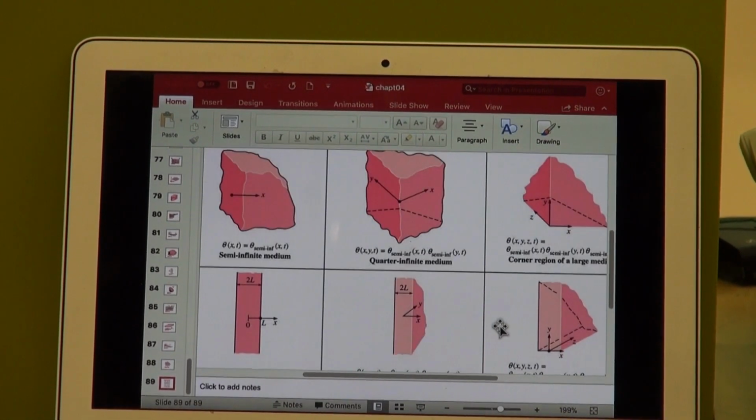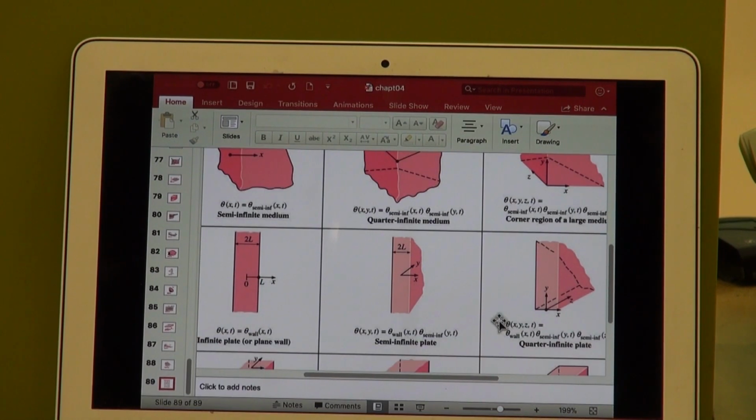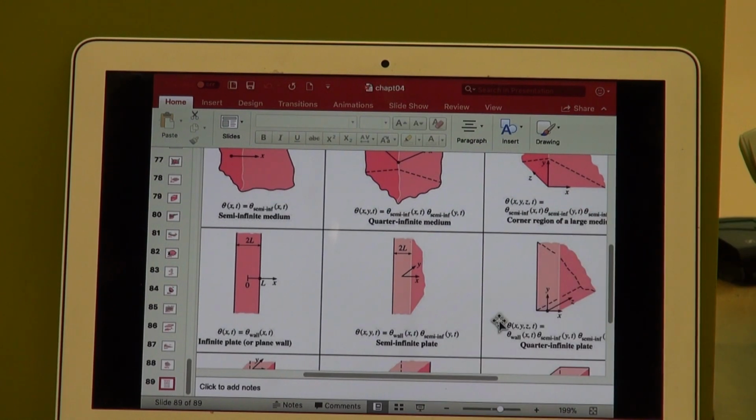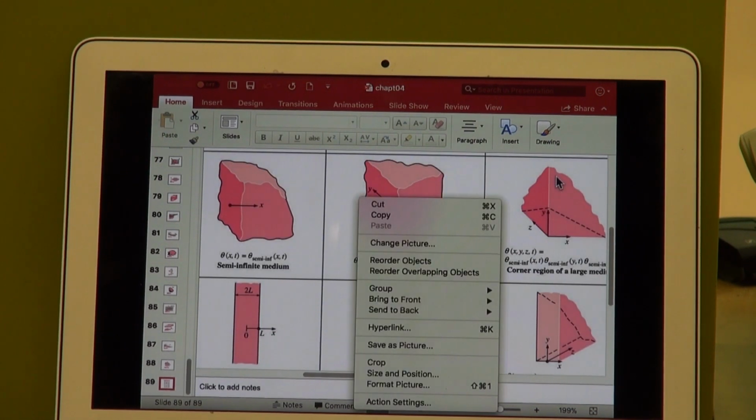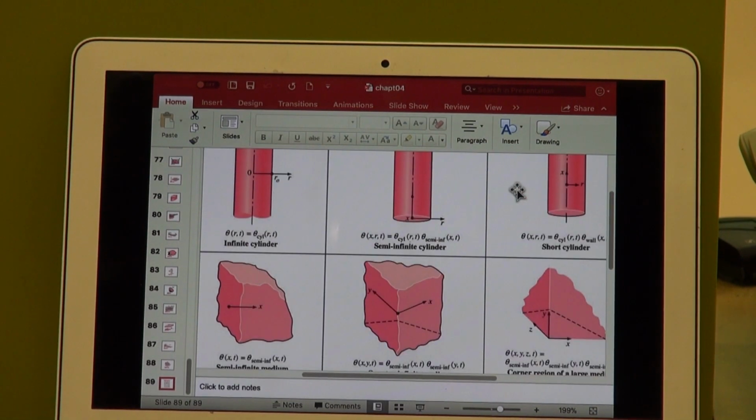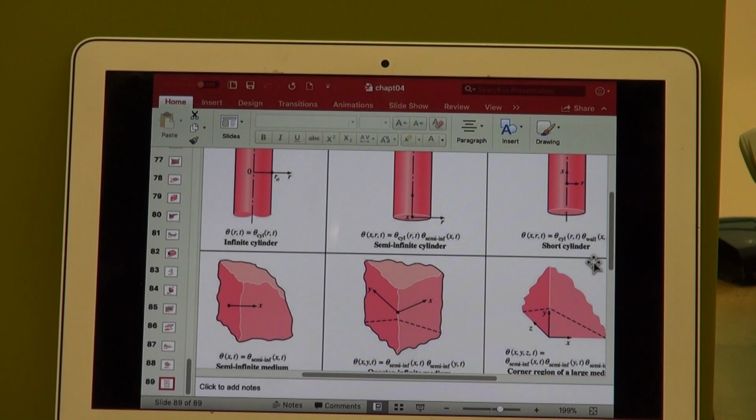Now, what is actually the secret or the most important thing to remember when you would like to use these types of solutions? It is to look very carefully at where the coordinate system has been placed. Where the coordinate system starts and ends is extremely important, because if they tell you typically it's the solution for a cylinder, then you need to use the equations that have been used previously for a cylinder.